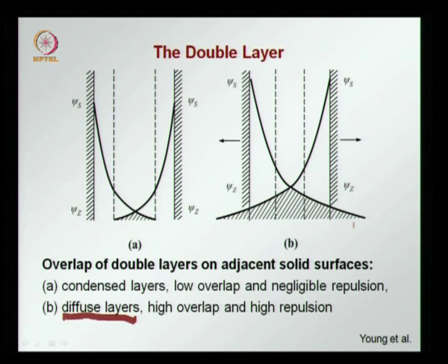And this is the basis of the design of plasticizers and superplasticizers which are meant to deflocculate cement particles. When the zeta potential of the system is higher there is better deflocculation, the cement particles remain dispersed for a longer period of time and you have higher workability.